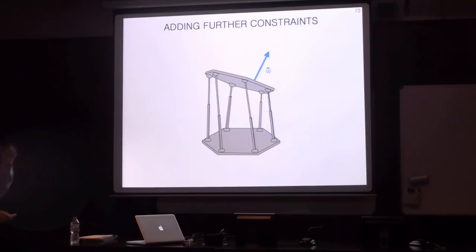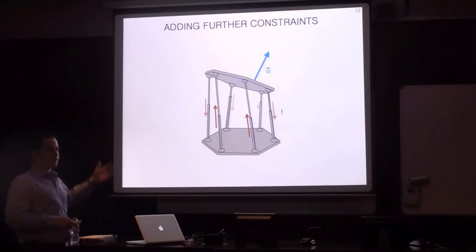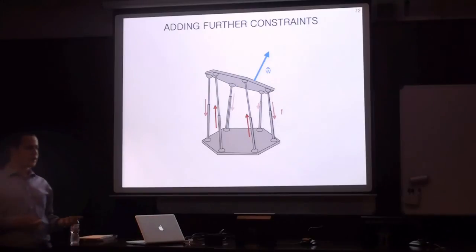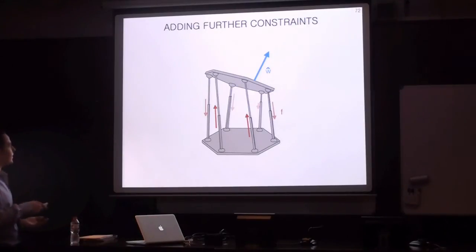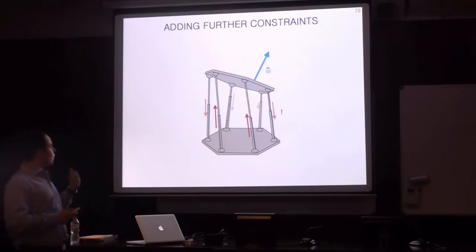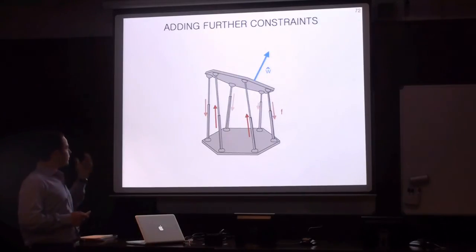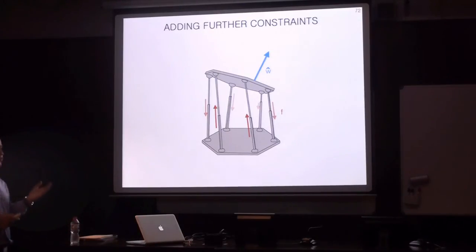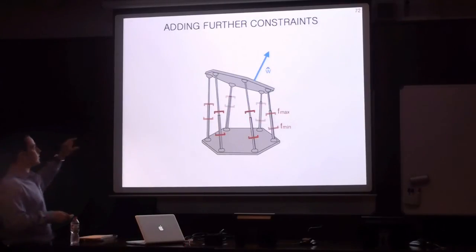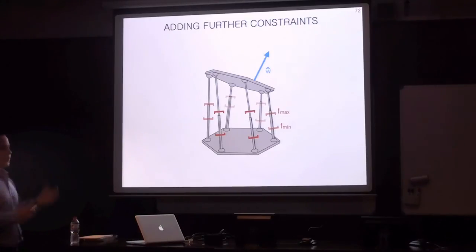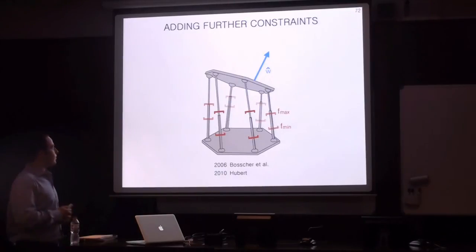It is known that given a wrench on the platform, this translates into some forces in the legs. And one problem near the singularities is that some of these forces can get very high, leading to breakage of the manipulator. So one way to stay away from these problems is to ask the platform to move while maintaining the forces always within their allowed limits. This is in fact inspired by the notion of wrench-feasible workspace in the works by Bosscher and Ebert-Uphoff.